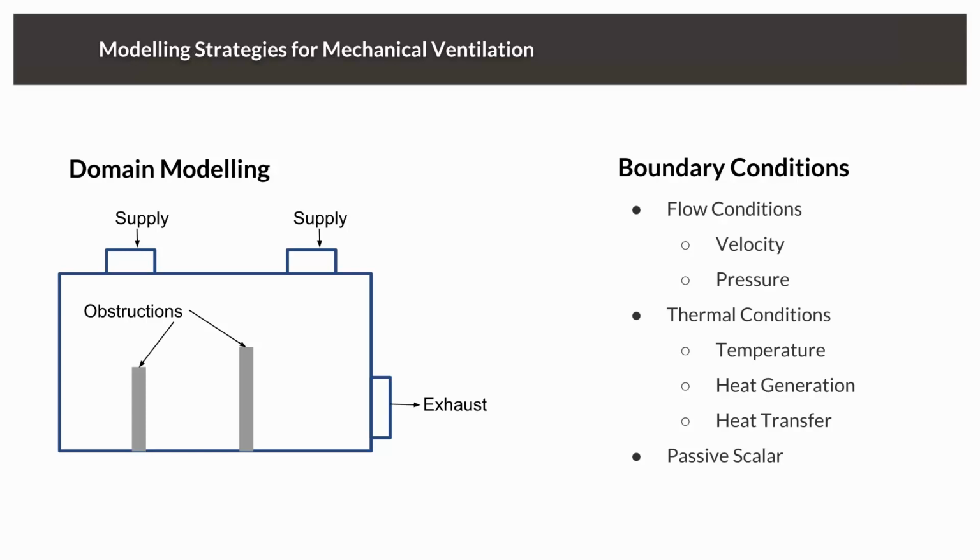Since we are not able to solve these equations analytically, we will do it numerically, which means we will take our fluid domain, reduce it to a lot of control points, and then calculate pressure and velocity only for those points.